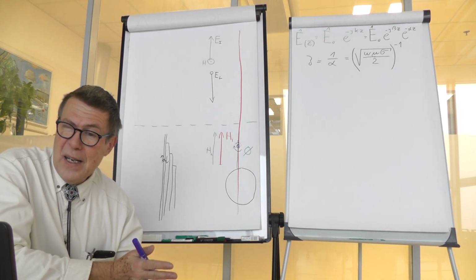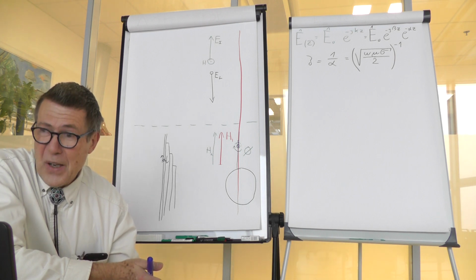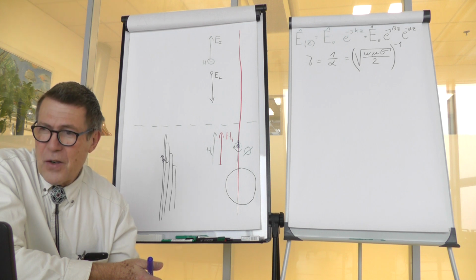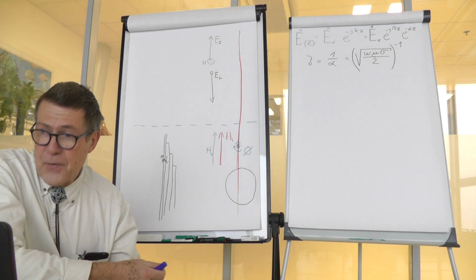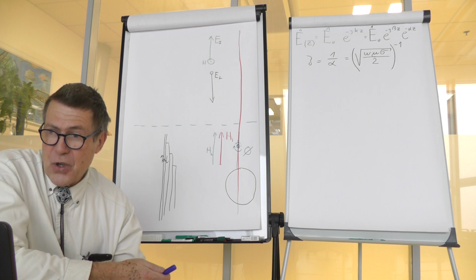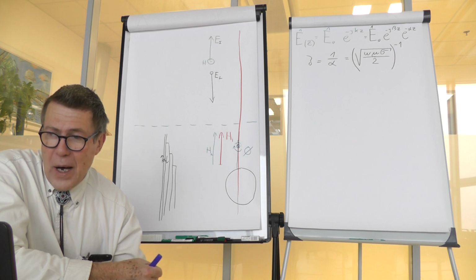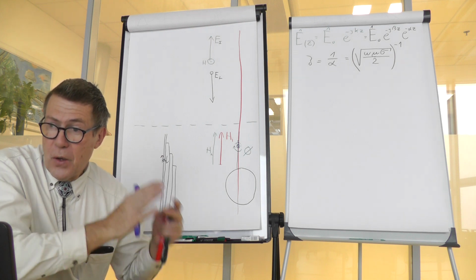If you have 100 times less frequency, then you have 10 micrometers. So even at radio frequencies of medium waves of AM reception, you have quite a small thickness through which the current really flows,